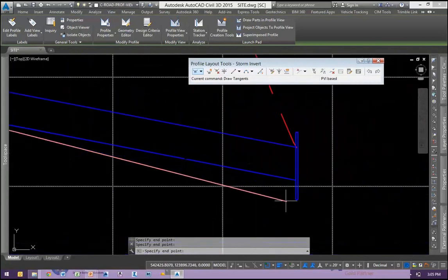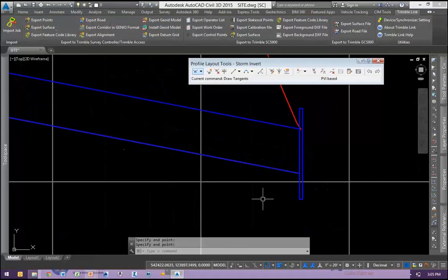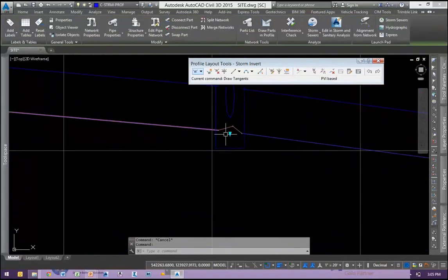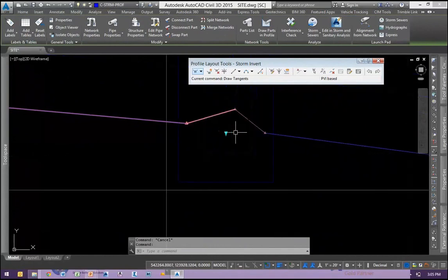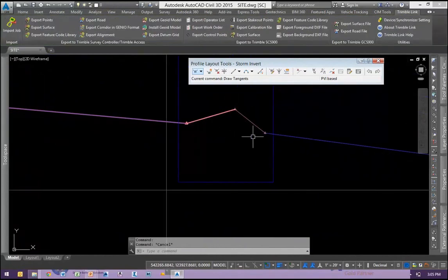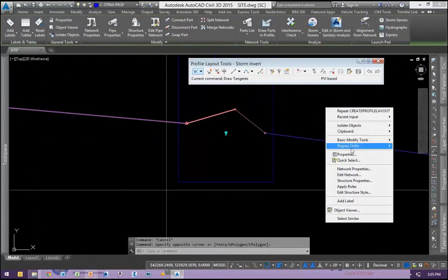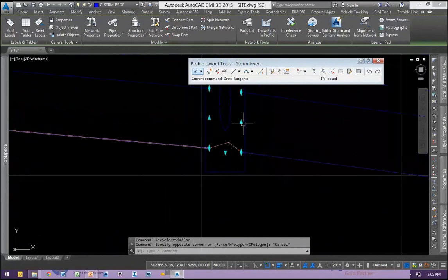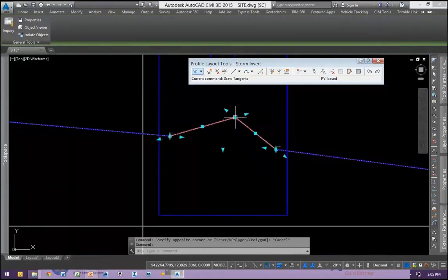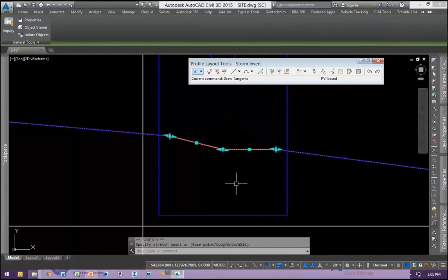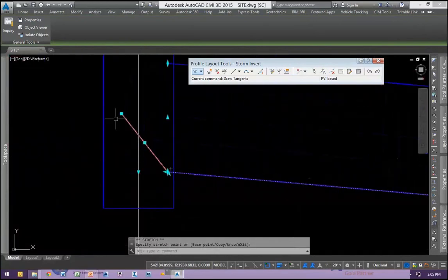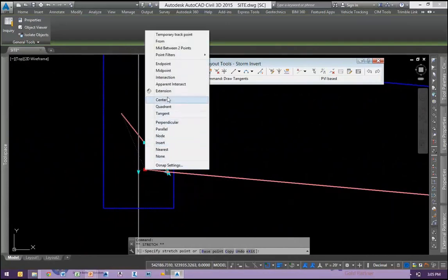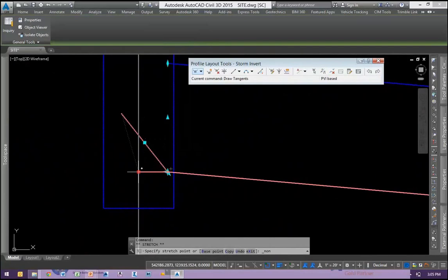So once I do this, if you guys have some suggestions, once I explain what I'm doing, definitely open to it. This is, right here is bottom of the structure floor. Invert is right there. There's no way to snap to that in an easy way. I can't turn that on. So what I find is the easiest for me to do, turn these structures on like this. Just grab this and do the magnetic snapping like this. Okay, a little tedious, but it's not too bad once we've created or turned on those pipe ends and everything like that.